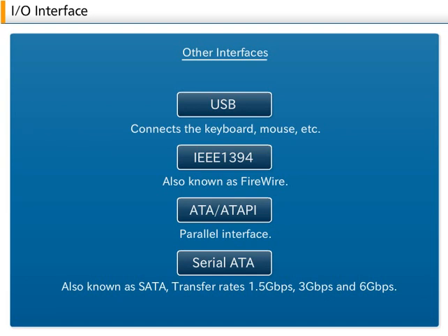Data transfer rates are 1.5 megabit per second in low-speed mode, 12 megabit per second in full-speed mode and 480 megabit per second in high-speed mode. It provides hot plug functionality which allows the plug to be removed or inserted while the power is on. In addition, USB 3.0 supporting up to 5 gigabit per second is announced.